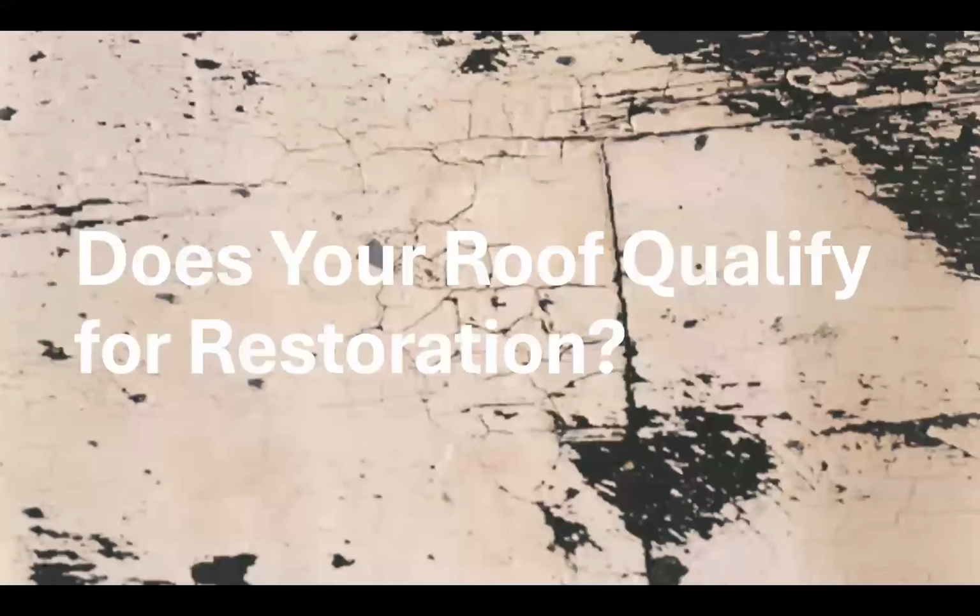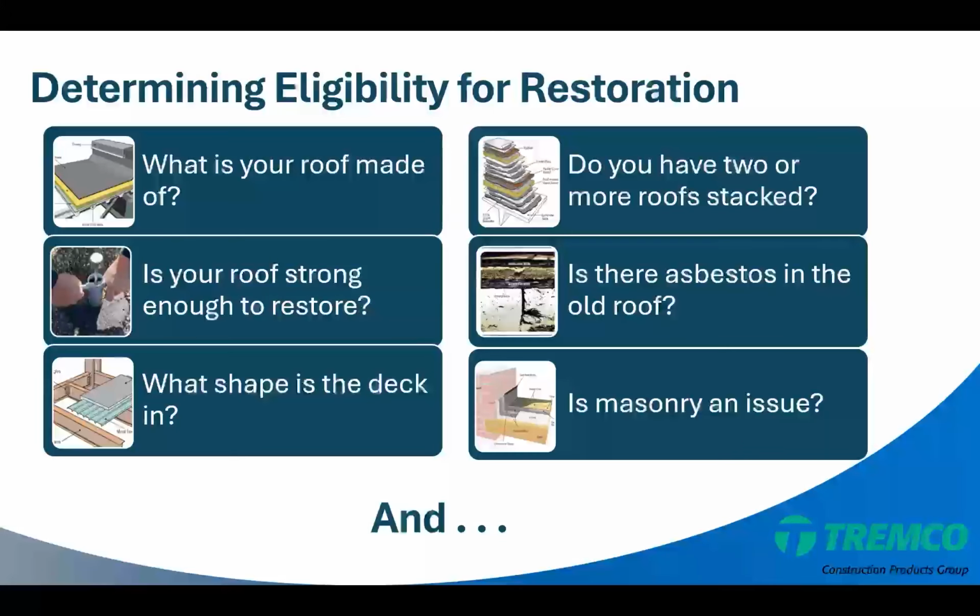So when we talk about roof restoration, what does it mean, or how do we look at whether your roof qualifies for restoration? Keep in mind that determining eligibility for restoration is not just a visual process. There are advanced diagnostics, inspections and analysis, ASTM labs, and testing that are crucial to determine if roofs or other systems are restorable.